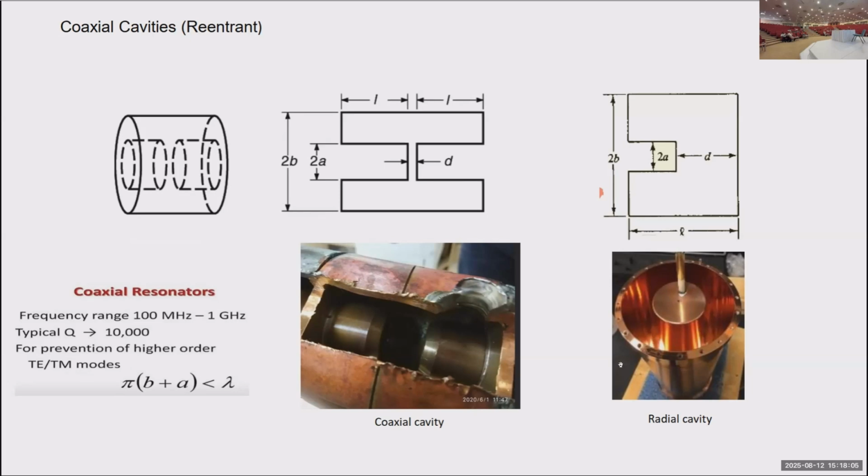I have explained a little before, that's a coaxial cavity, of course, cut at both ends, and the small part acts as a capacitor in here. And that's the real coaxial cavity, the re-entrant cavity. What's a re-entrant cavity? A cavity is a space covered by matter. Some of the surfaces go into the inside, and you get a new shape.